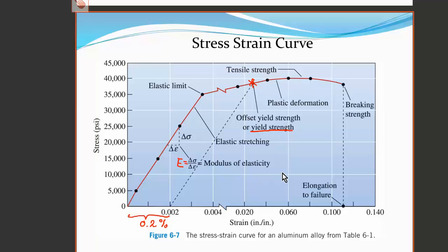If we create a stress in the material which exceeds the yield strength, sometimes given the symbol sigma sub y, then the material will be permanently deformed. In most engineering applications, we want to avoid ever getting close to the yield stress of the material, because that will permanently change the structure.